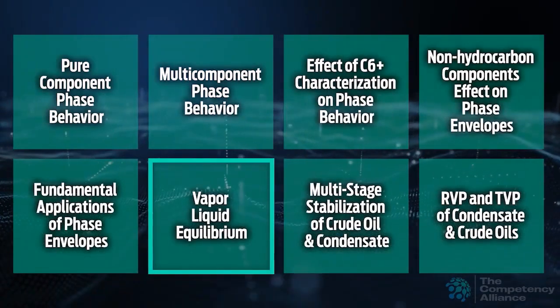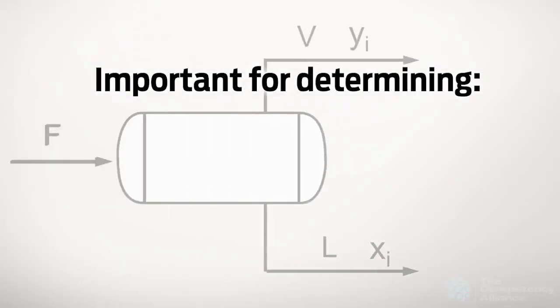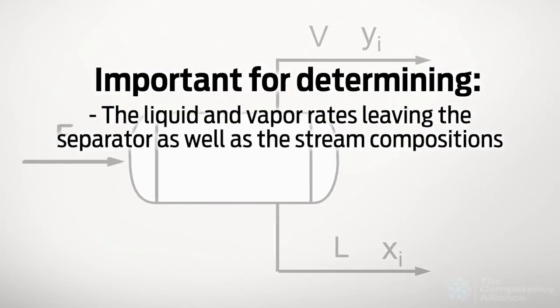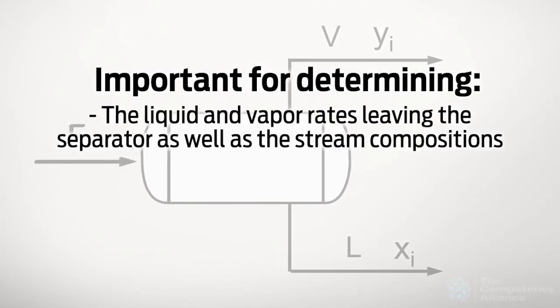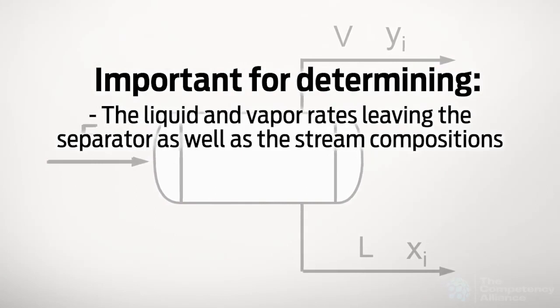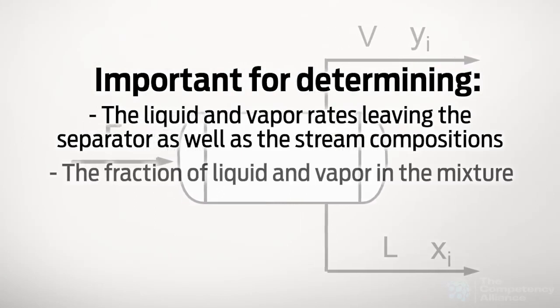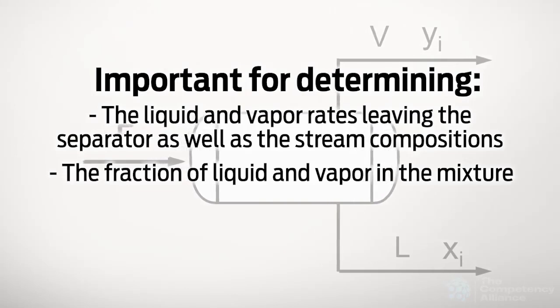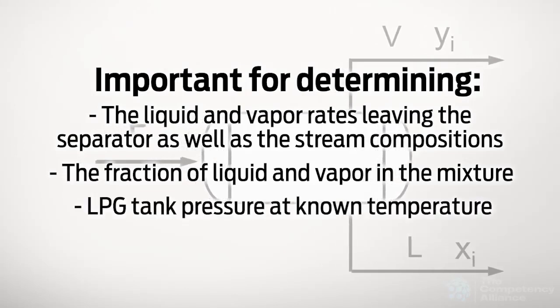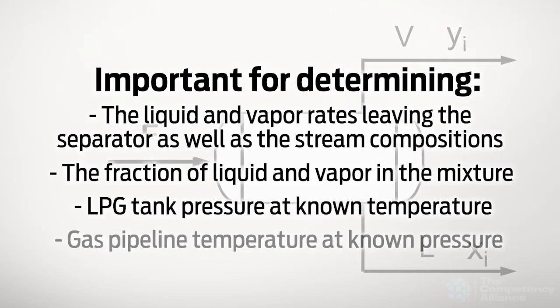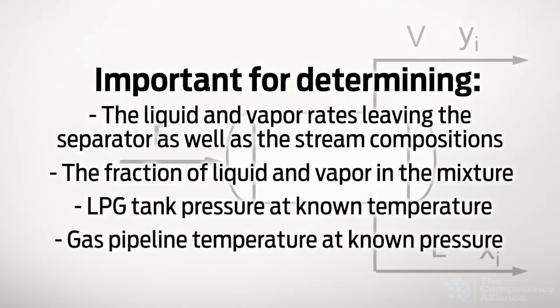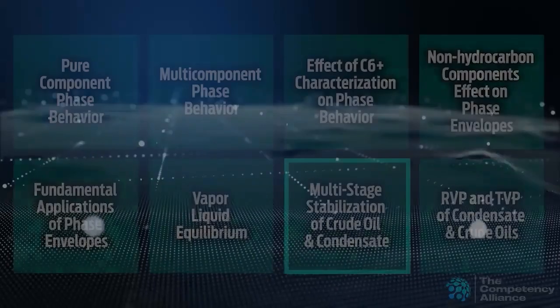Performing VLE calculations is important for determining the liquid L and vapor V rates leaving the separator, as well as the stream compositions xi and yi, the fraction of liquid and vapor in the mixture, LPG tank pressure at known temperature, gas pipeline temperature at known pressure, etc.